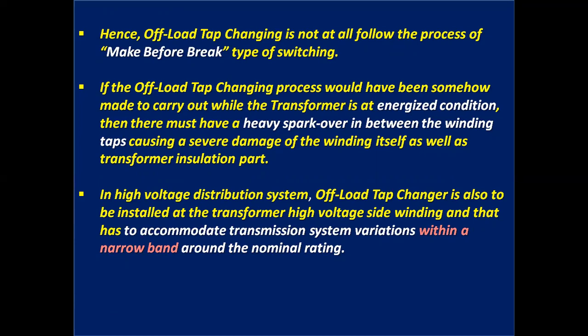In high voltage distribution systems, an off-load tap changer is also installed at the transformer high voltage side winding, and that has to accommodate transmission system variations within a narrow band around the nominal rating.